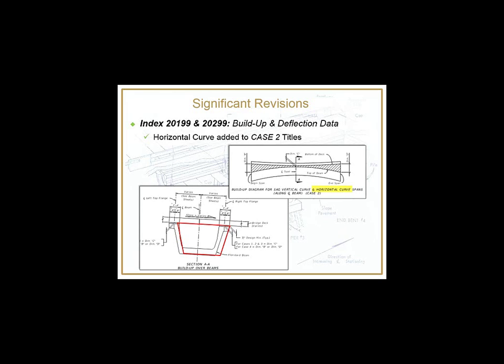But due to the curved alignment and the chorded alignment of the pre-stressed beams, there is the effect of essentially a sag at mid-span for the build-up above the top of the pre-stressed beams. So that needs to be considered when calculating the values for the tables and the weights of additional concrete on top of the pre-stressed beams for design. So that applies to both I-beams and U-beams.